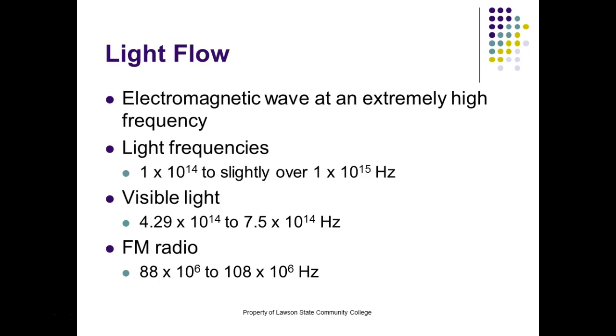Originally, when they started broadcasting, they did the amplitude. But what they found out real fast is that electromagnetic interference changes the amplitude. So this is why AM is so noisy. AM hums all the time, because of 60 cycles all over the place. It's real hard for EMI to change the frequency. So this is why FM is so popular, because it's real hard for EMI to get to it. You know what EMI is, right?